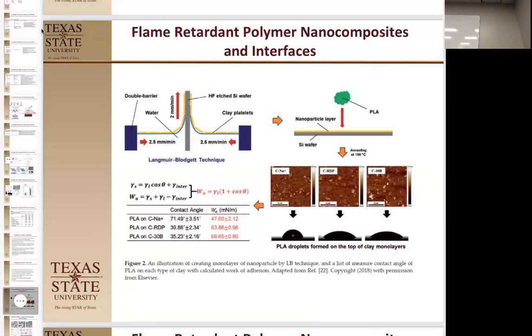Okay, in a Langmuir-Blodgett technique, what you do is you take a bath of a fluid, preferably a fluid your material does not interact with, a fluid with high surface tension, usually water. You then have gates on it, and then you have a sample dipped into it. Then you continuously push the things in, and you're looking with microscopes to make sure that the entire surface is covered in exactly one layer of molecules. So you have one layer of molecules.